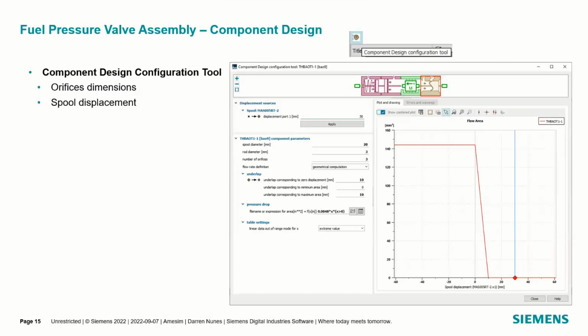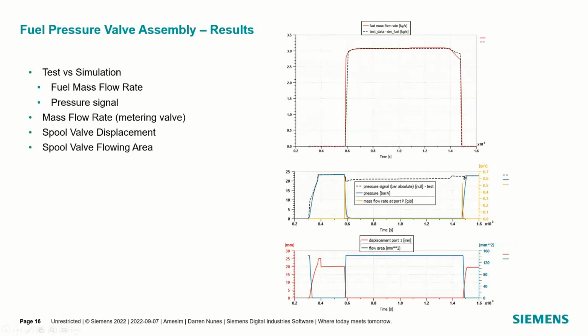So we wanted to really just avoid any flow leak in that design. So back to the comparison, we have those flow rates from our tests, our fuel flow rate or even our pressure signal that we got from literature, and you're able to see from matching that how it's going to alter our flow rate in our different valves, how it's going to alter the pressure in the different locations, and we can see what the different displacements and flow areas are of those valves themselves, right?